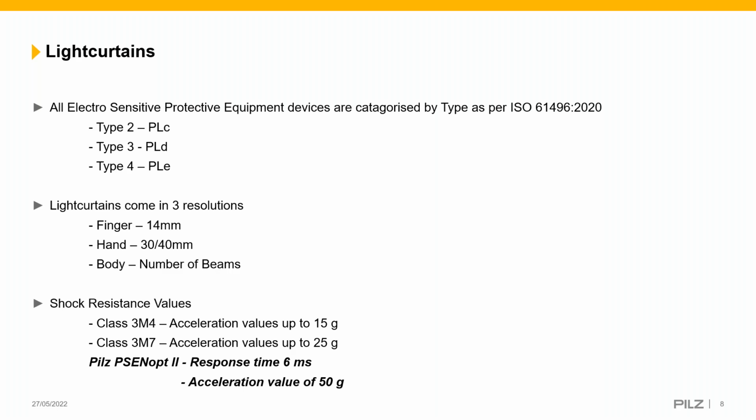Previous to the 2013 version, type 2 devices could achieve performance level D, and that meant that they were very often used in robotic applications, because 10218 specifies that you need PLD Cat 3 for all safety related parts of the control system. But back in the 2013 version, released 2015, that was declassified to performance level C.